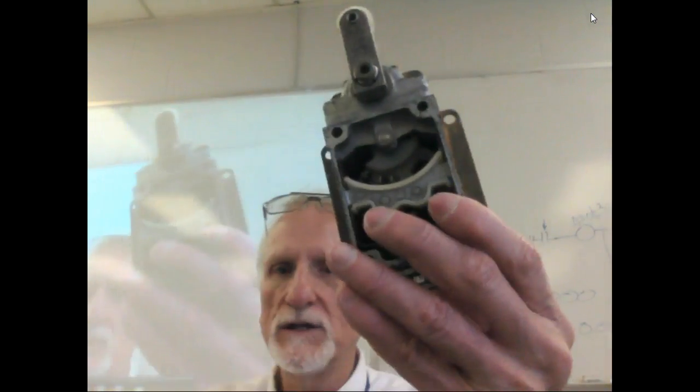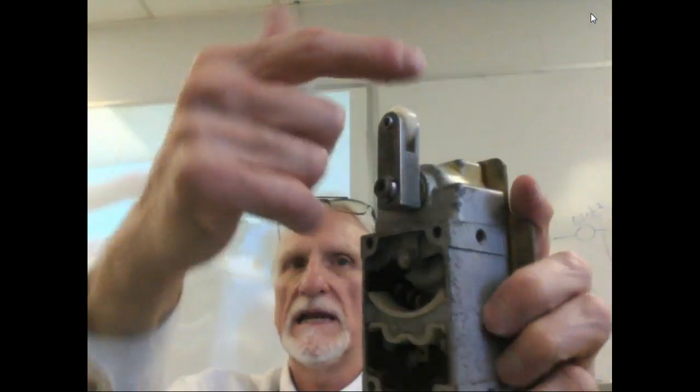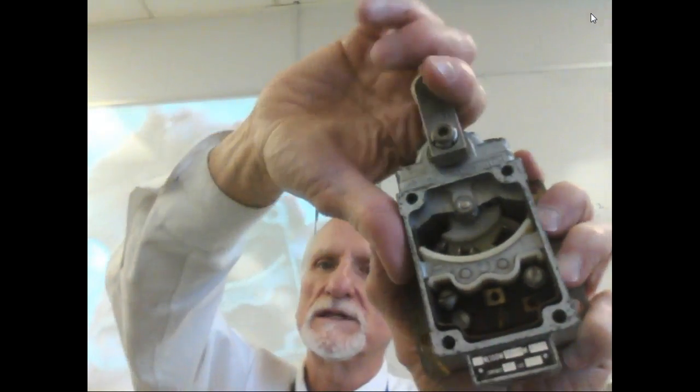go. So this is a heavy duty, or what we call a pilot duty, limit switch. So we usually have a cover right here, and then the connection runs up into here. And then it has an operator. We can get different operators for the limit switch. And when something comes along and hits this, you can hear it actually click. It's got a little unit in there, kind of a plateau. It won't switch, and as soon as it clears that plateau, it snaps.